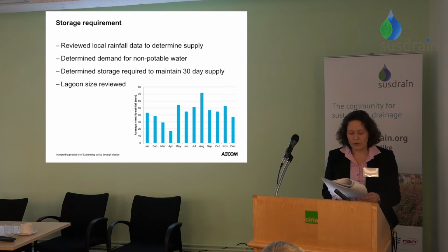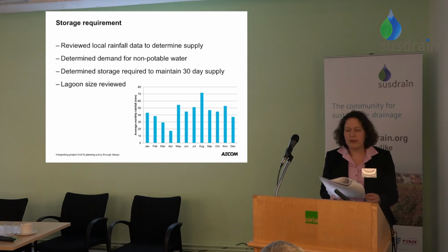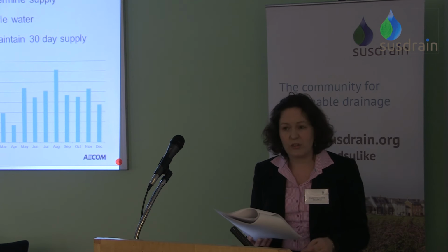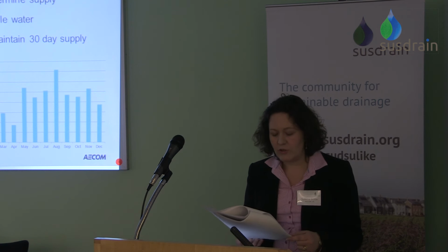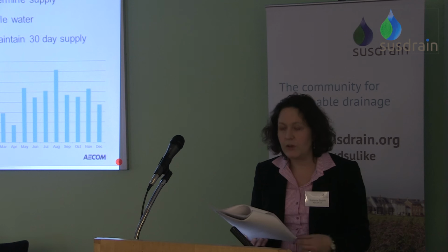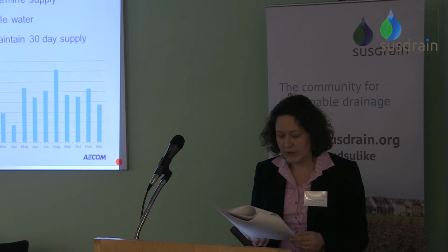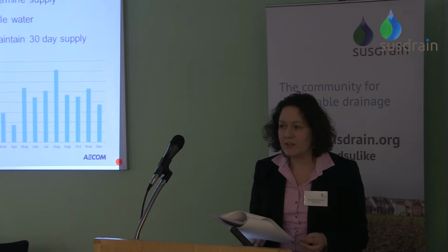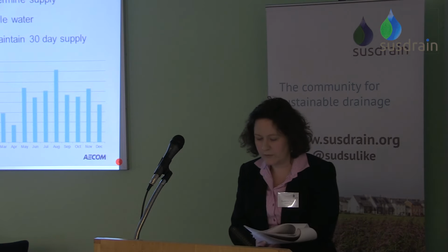The larger of the volume to restock that supply or long-term storage was taken forwards into the strategies. Unlike most developments, infiltration was discouraged at Cambridge, partly due to the geology, but primarily to maximise runoff volume from plots into the network for use within the non-potable network. Swales were lined. Attenuation in the form of blue and brown roofs was permitted, but green roofs were discouraged.